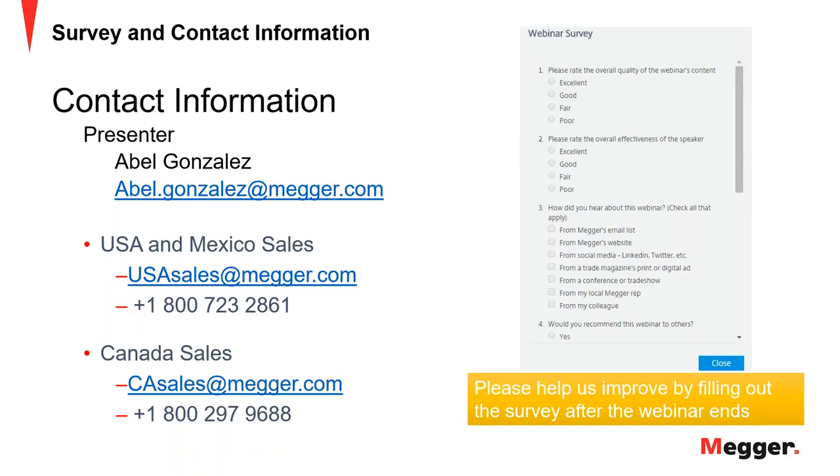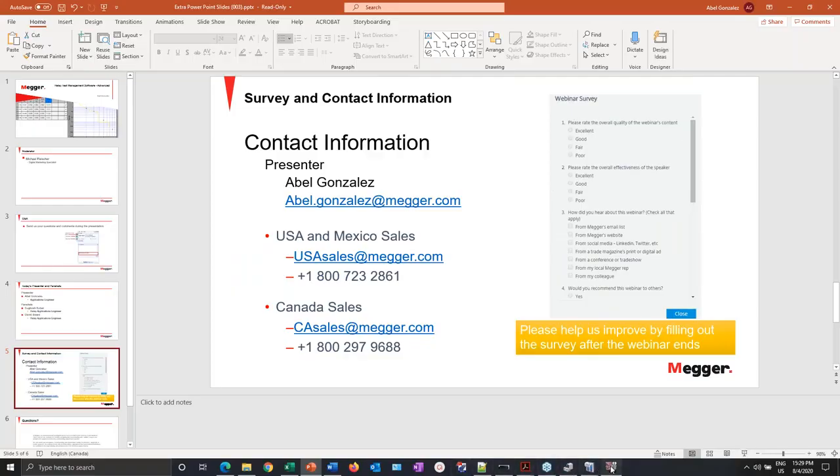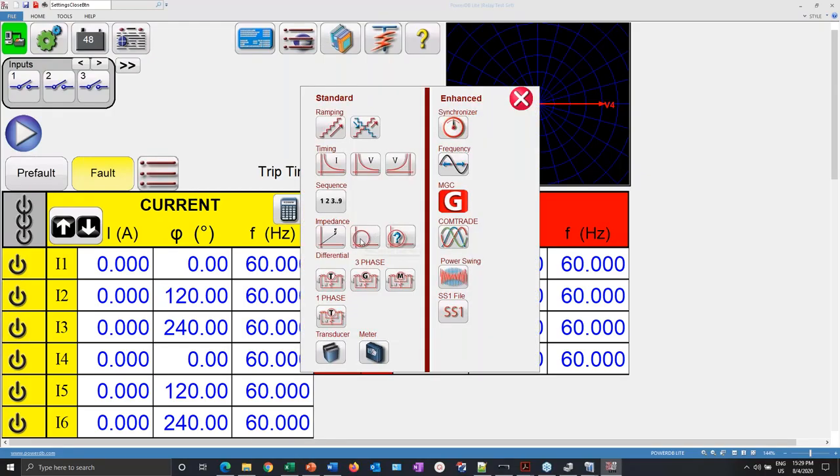Sugosh Kuber will be answering our next question. Sugosh, I see that there are 3 options provided in RTMS to test impedance relays. Could you advise on what method to choose when? Yeah, so the 3 options provided are called the EZZ method, the COF method, and the third one is the undefined characteristic method. The EZZ option provides more of a manual approach to perform basic impedance relay testing. The second method, the COF, is the click on to fault approach. This particular method, I would say, provides the most flexibility and complete test capability.